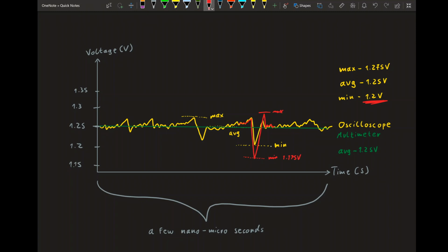which even most oscilloscopes can't see. Like the oscilloscope I have, for example, takes 1 gigasamples a second, so it can take 1 billion samples a second. Well, if your part runs at 5 billion cycles a second, then you only see every 5th cycle. And your resolution is kind of bad because you can't really tell what's happening in between the cycles, you just see a peak or a valley or something. So that's why the oscilloscope right here is set to a scale of nano or microseconds, because that's what a normal oscilloscope can actually see.